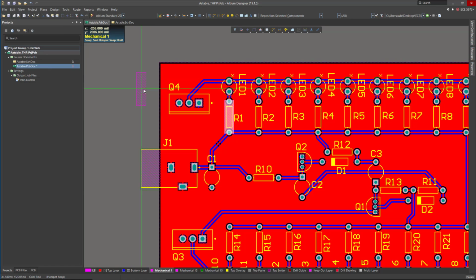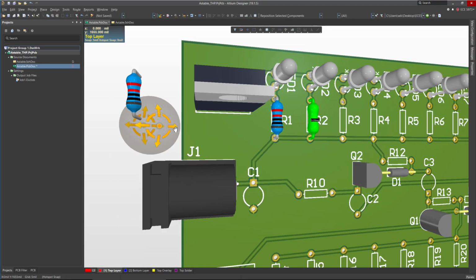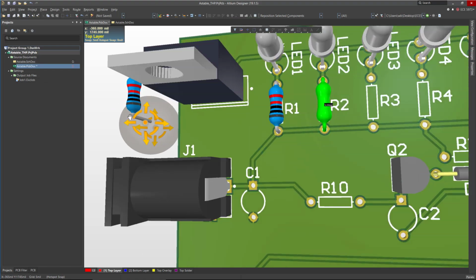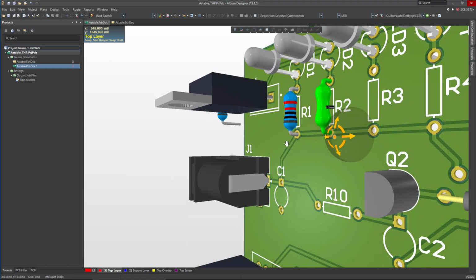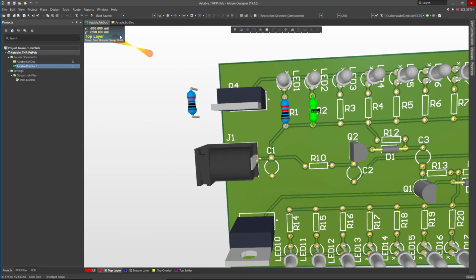This is the 3D model. Now you can paste it over the second component and third component and so on, and try to align it. So let's place it here. Let's switch to the 3D view, and that's it. This is how you can copy a 3D model. You need to align it to remove the collision. You have a collision in here. This can be cleared, it's not a problem. But this is how you copy it.